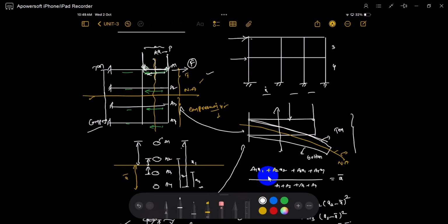But we made some assumptions for calculating this force in that zone. This is an assumption: we assume that the moment in this zone is equal. So how can you make it equal? It varies from P to P multiplied by x, where x varies from this to this. So we made the assumption that we will take the average moment on that zone.